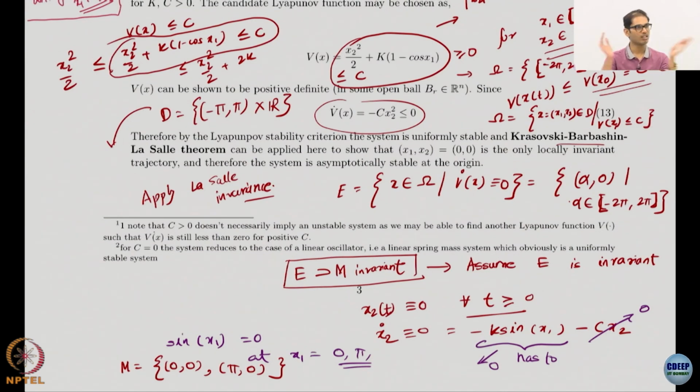So that is all. I shrunk the domain so that I have one equilibrium in this domain, and then applying Barbashin-Krasovsky-LaSalle is very easy, because the set E remains the same and the set M contains only the 0 equilibrium. That is the proof that 0 is asymptotically stable, not global because of this restriction in the domain, but whatever, it is asymptotically stable, more than enough.